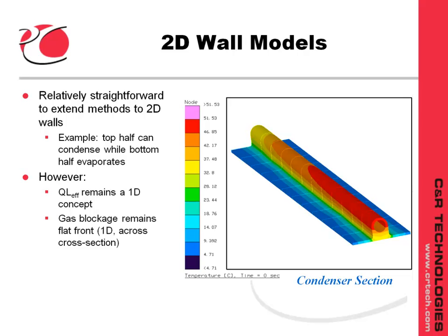It takes contributions from each circumferential segment along the way, but since it's only measured axially, the FloCAD base tool won't predict a transport limit from one side of the pipe to the other, just from one axial location to another. Now that's not an issue for tube-shaped traditional heat pipes, but it does complicate the estimation of limits for vapor chamber fins, which can otherwise be modeled as 2D heat pipes using FloCAD.